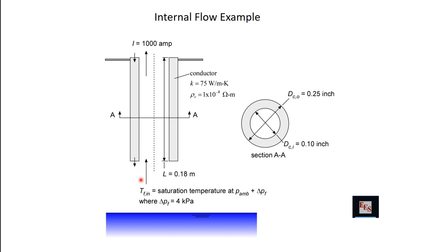The vapor is typically generated by boil off of whatever cryogen you have submerged your superconducting magnet in. So in this particular case, we're going to assume that we have a Dewar, and it's filled with nitrogen. So there's a liquid nitrogen bath basically somewhere in the Dewar. And then as there's heat leak to that bath, or there's heat coming through the magnet, or there's heat being generated by the operation of the magnet, all these different places that it can gain heat, it's going to boil off.